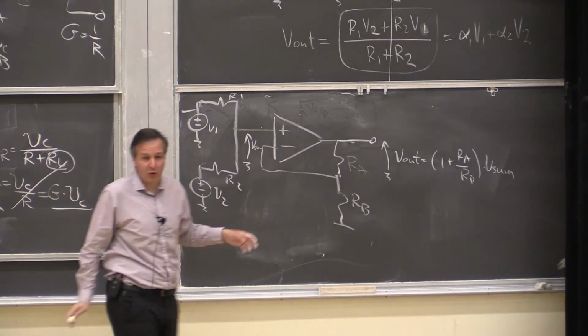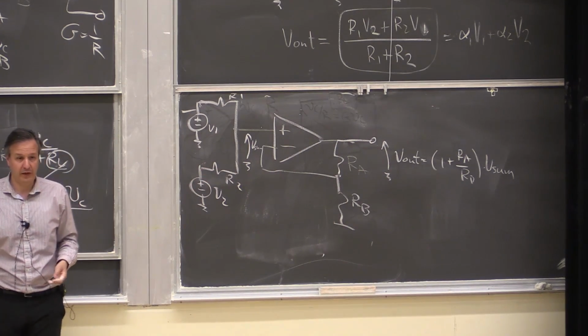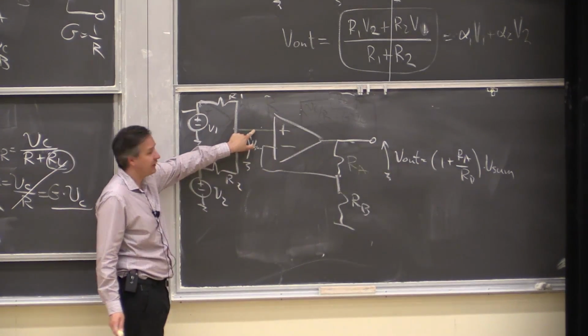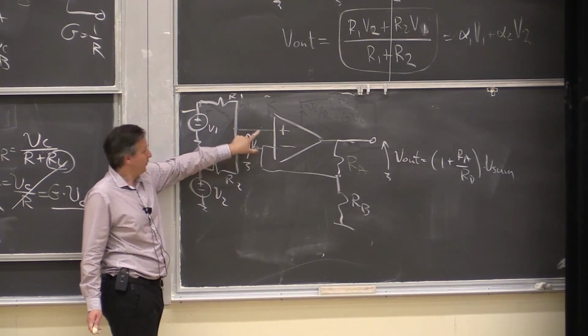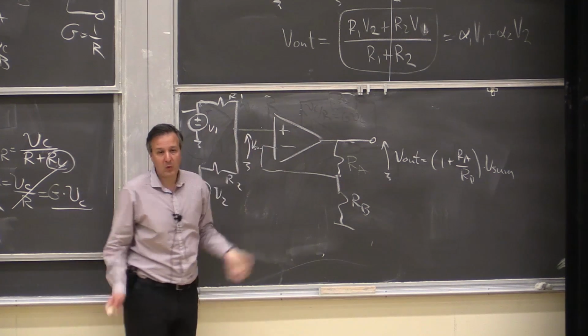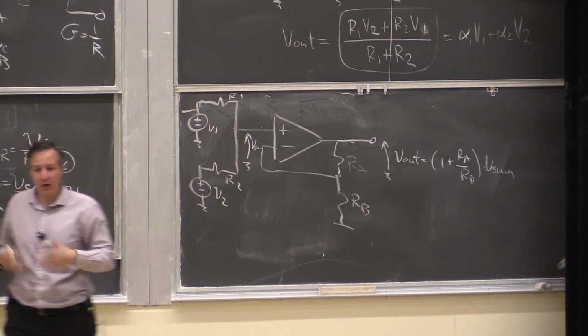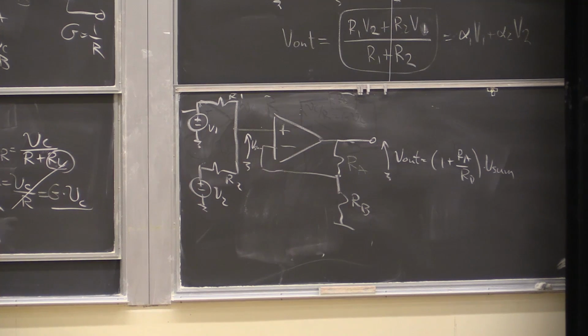So I don't even need to solve these things. It's just block composition, and I can do this because current here is 0. So these non-inverting guys, they're composable. I can just add them to the previous block. They just measure the voltage. It's all good.